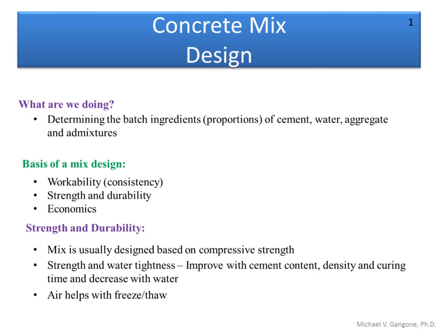Now, we do know that there are some trade-offs when we have air entrainment, right? Because with these chemical admixtures, we induce little air pockets, air voids, we create void spaces, and we know when we create those void spaces, that can reduce a little bit of the strength of the concrete. So there is a balance or a trade-off, so to say, between using air for durability and the fact that when we use air, we can minimize the strength a little bit. So there is that trade-off that we will see.